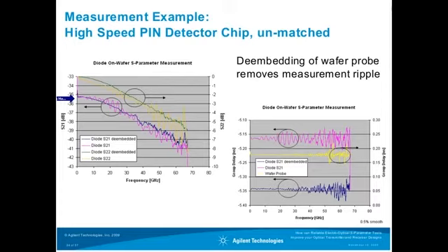Also, removing the wafer probe means extending the reference plane, and extending the reference plane also removes the transmission delay imposed by the wafer probe.